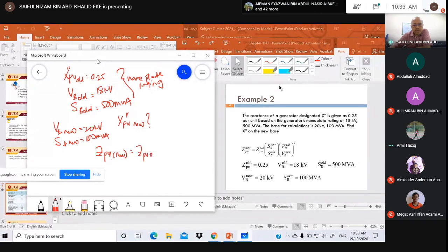Z PU old times kV old over kV new, square, don't forget square, times MVA new over MVA old.